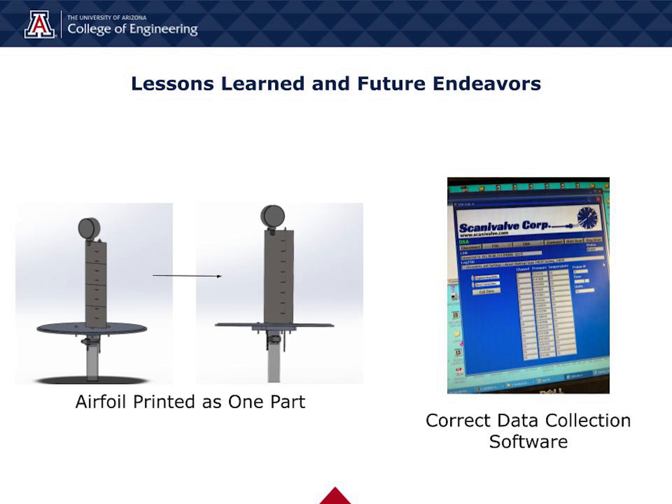Given more time, conducting tests at higher speeds would provide valuable insights into the performance of the airfoil under more extreme conditions to further validate the design's effectiveness in minimizing the wake across a wide range of operating conditions. Integrating pressure sensors along the suction surface can provide essential data on pressure distribution, further facilitating the refinement of the design.